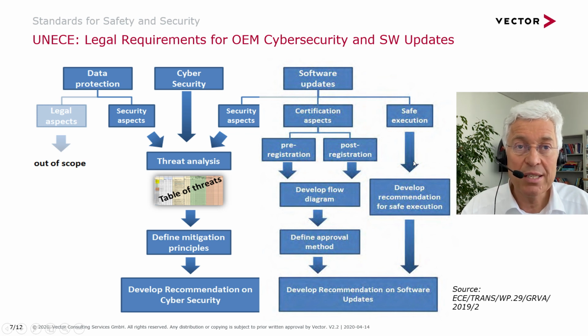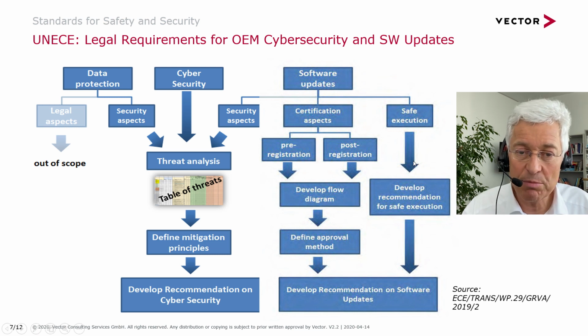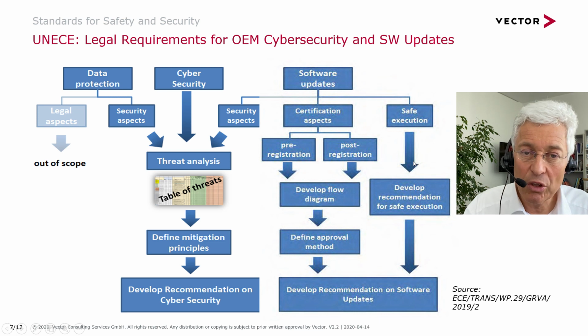We also have software update management on the other side. Why? It's clear that we have an increasing amount of software which comes directly to the vehicle, which is either adaptive, or learns from situations, or is just updates, like a patch or a functional enhancement. All these updates have to ensure that we will not violate the previous type approval.